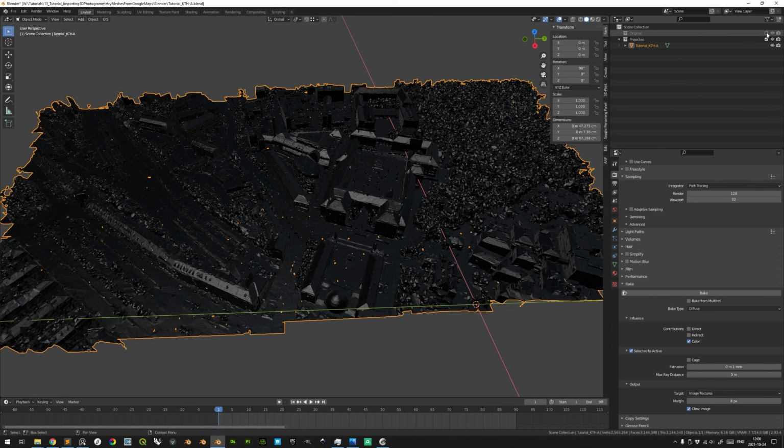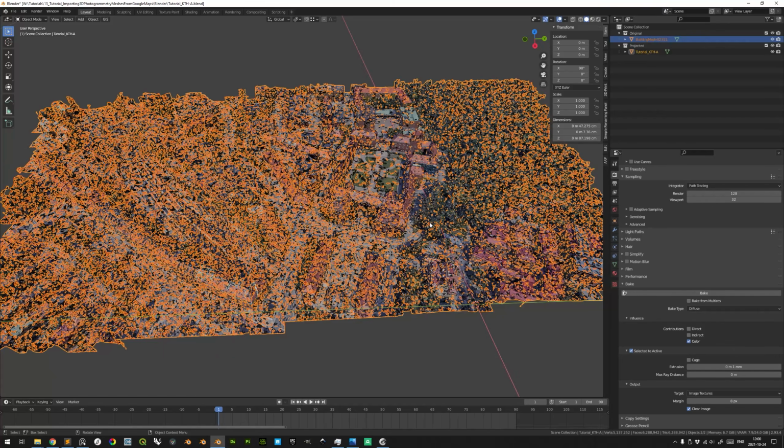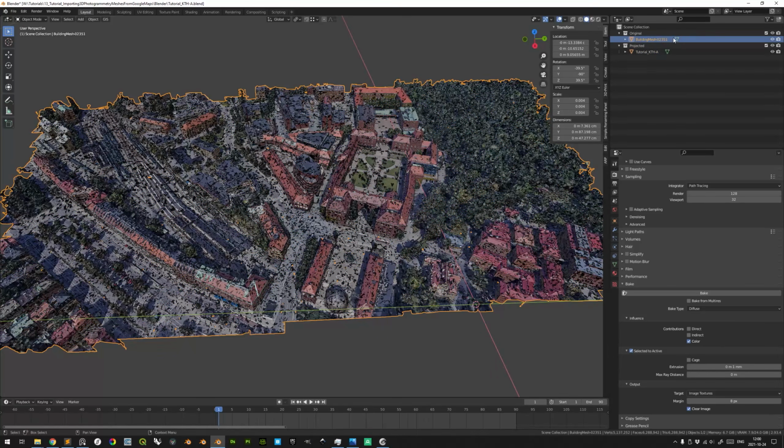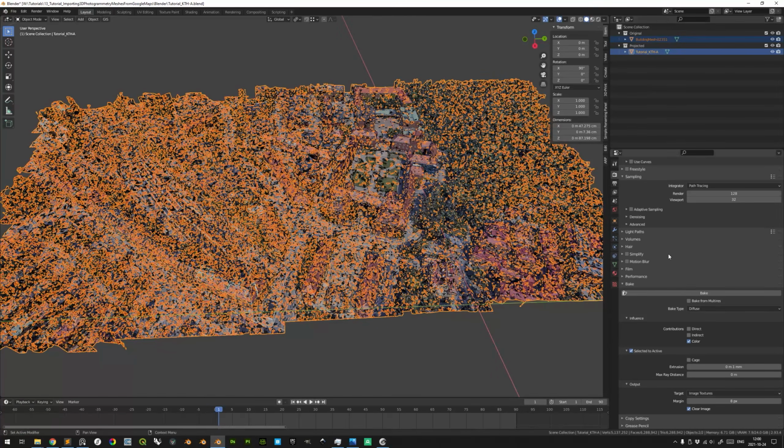But we will project the color values of all of these textures onto it. All right, so select this one, control click this one, and let's make sure to retain the extrusion distance based on the actual geometry and not on the UV texture, but the margin is of course dependent on the texture. So we'll increase this, since we doubled the resolution from 8K to 16K, we'll double the margin to 16 here. All right, and then we can bake.